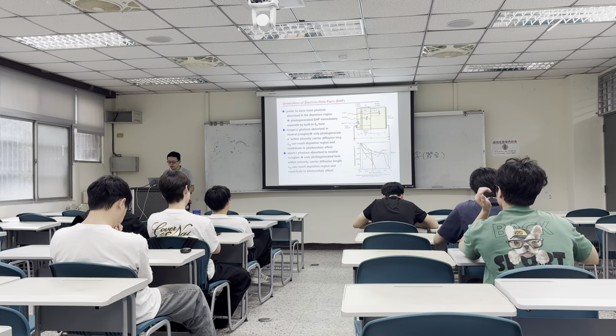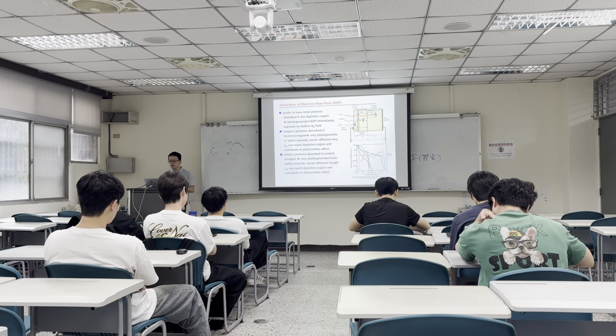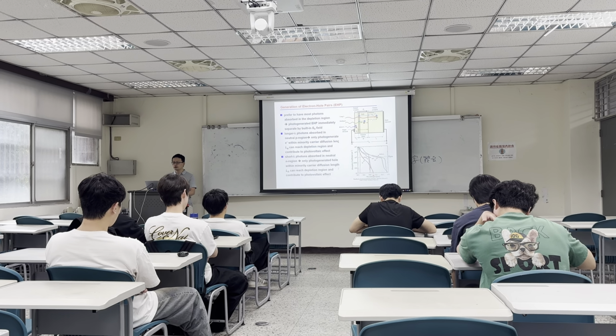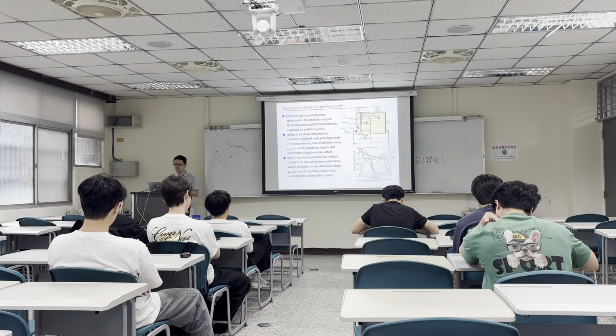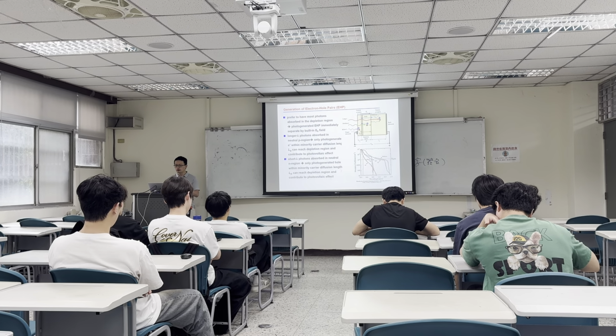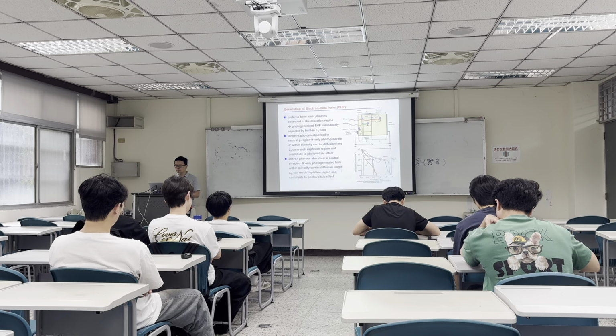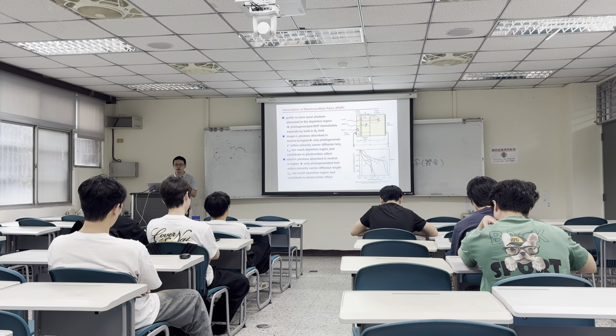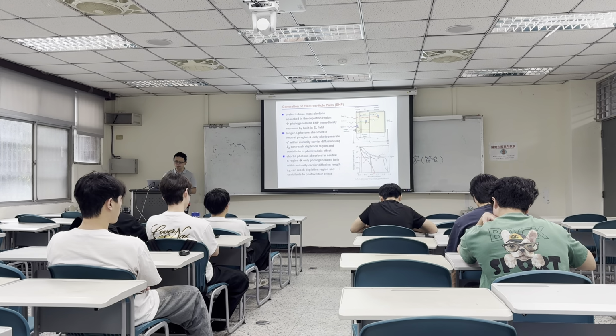Okay, but for the so-called longer photons, like 900 nanometers to 1.1 micrometers, the absorption depth is more than 200 micrometers, sorry, 200 micrometers. That would be out of range for the thickness of a silicon solar cell. So all those photons will have no contribution to the photocurrent.